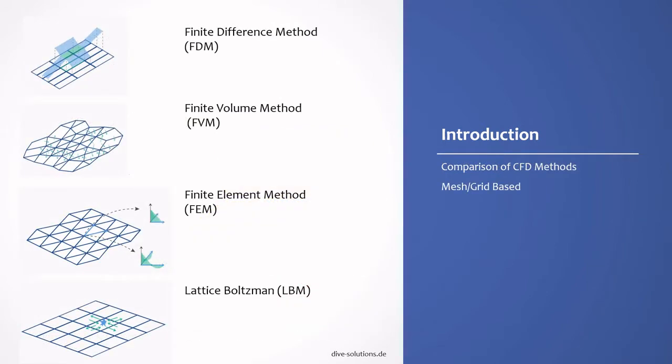Computer simulation of physical phenomena has been an important part of engineering and science over the last several decades. It is a method used to test theories and hypotheses. Mesh-based methods such as finite difference method, FDM, finite volume method, FVM, and finite element method, FEM, apply to many areas of what we now call computational fluid dynamics or computational solid mechanics. These methods shown here have proven to be very practical for solving differential or partial differential equations of the physical properties of matter and energy.